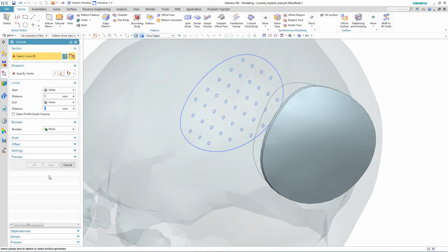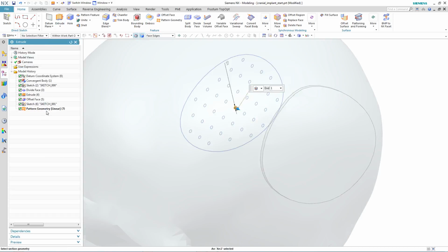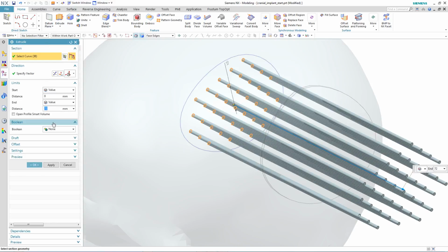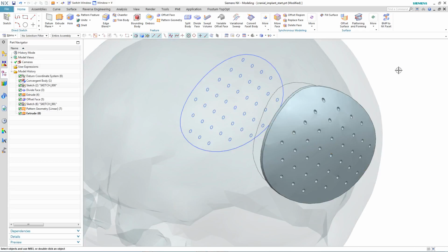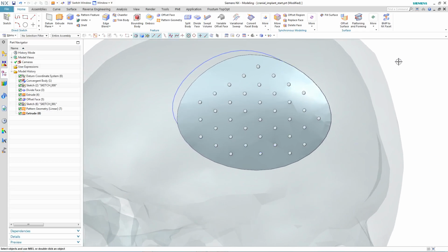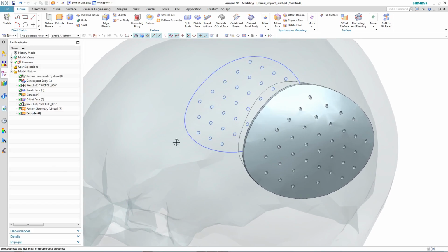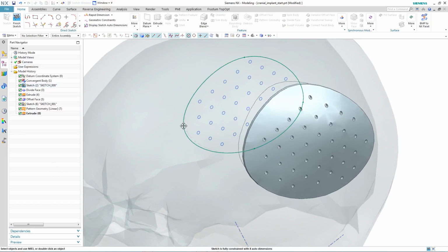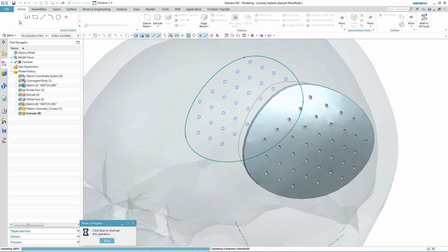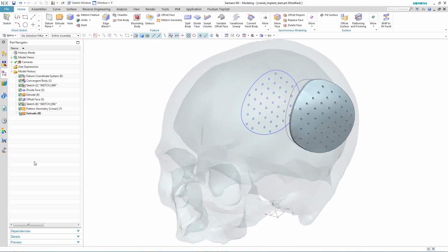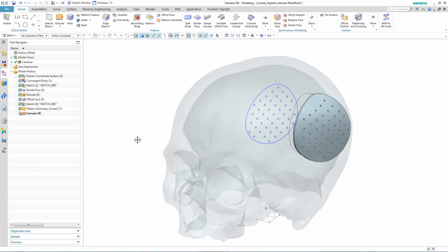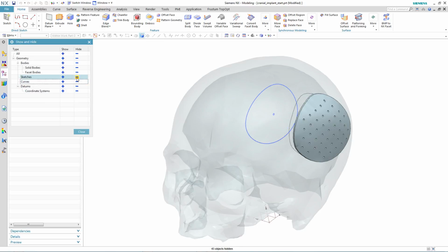Finally, we'll extrude the sketch and the pattern geometry, make sure it protrudes through our patch, and then subtract directly from the faceted body. The other beauty about convergent technology is that there's a level of associativity. So again, if we make a change to our original patch profile, then the faceted body and all the actions that were performed on the faceted body would update.